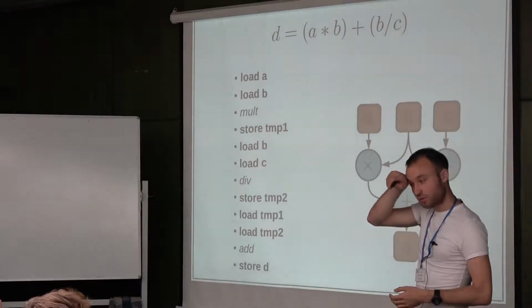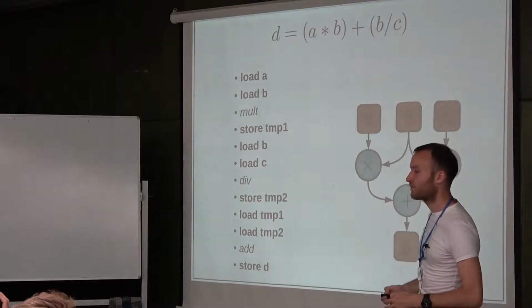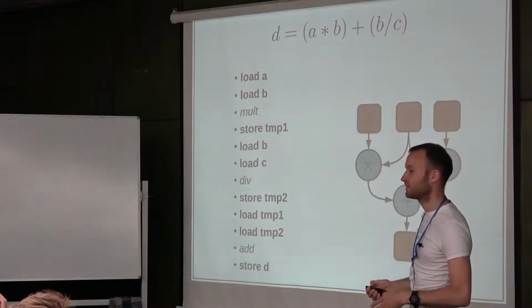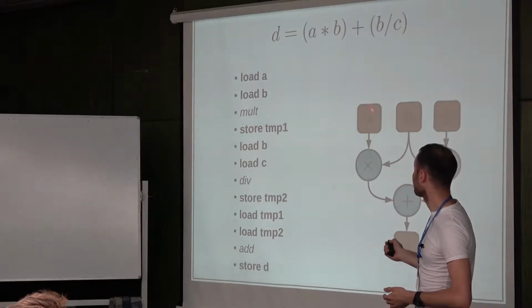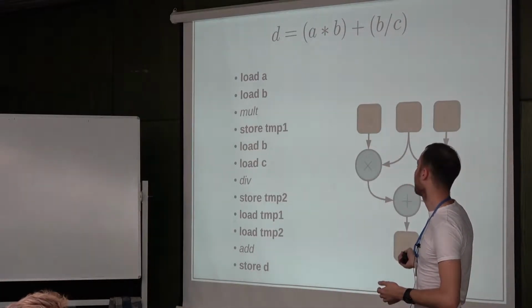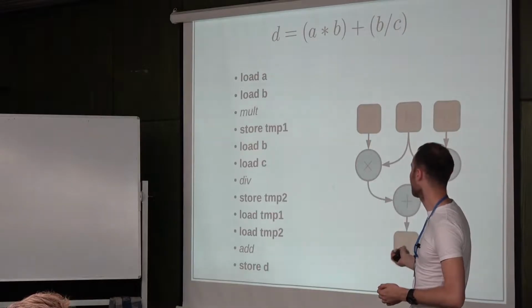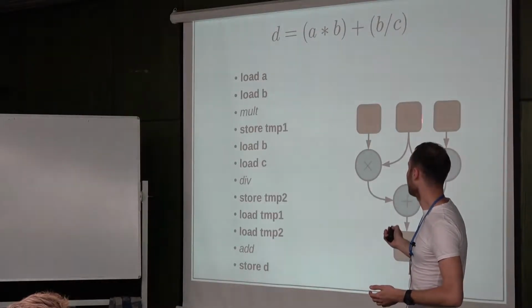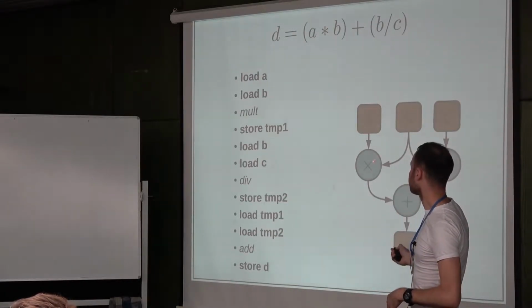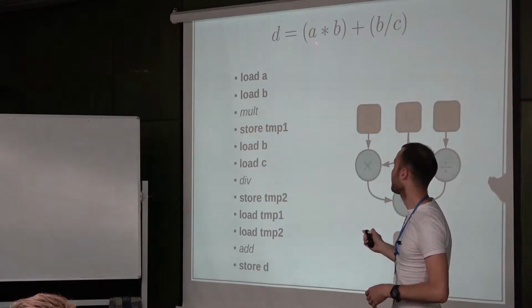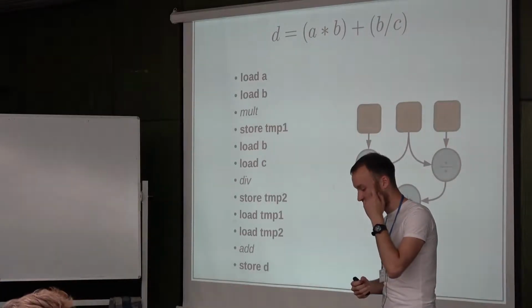With the reconfigurable approach, what we would normally do, we will synthesize registers. So these are flip-flops. So throughout this talk, I will use registers and flip-flops interchangeably. So this is essentially the same thing for our application. And we physically synthesize required units, and we build a tree. So it's not homogeneous as was the case previously. So we have different units, but still the principle is the same. We have different units, and we can implement flow. Also, in case we have vector operation, we can pipeline these operations, and this is the circuit that we would build for that.